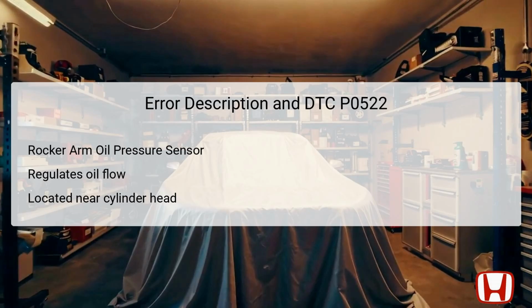When the system detects low voltage, specifically about 0.18 volts or less, it leads to the DTC P0522 error code being logged. This condition can result in ineffective oil distribution, potentially causing increased wear or damage to the engine components.